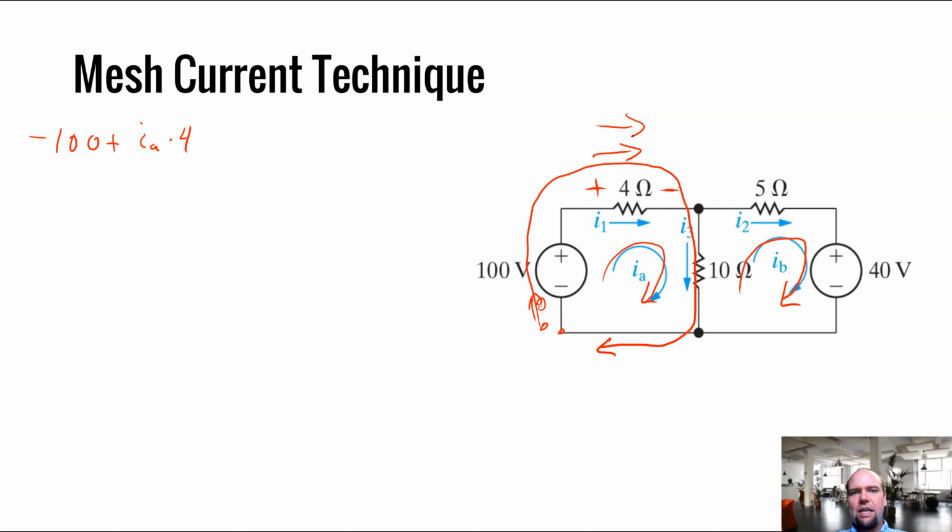So sometimes I'm simultaneously picking a current in a direction to correspond to a voltage in a direction that I want, such that I can still use the equation V equals IR. In this case, I'm looking for the voltage drop, and I'm going to use the current in this direction, which means I use the V equals IR version.